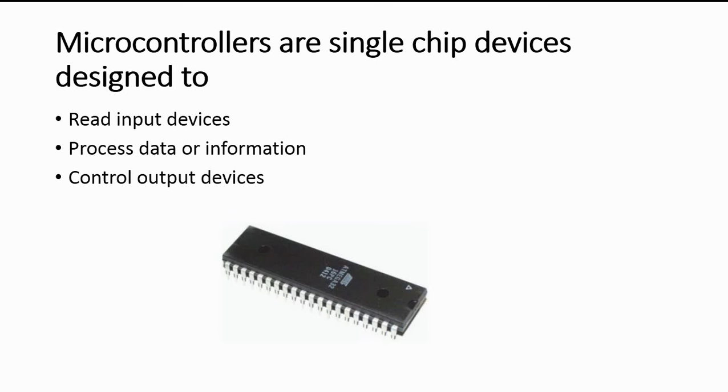some years ago they were not used for high voltage applications like home or industrial automation, where we have to control high voltages like 220 volt or above 220 volt. Because our generic relays or the electromechanical relays have a disadvantage of producing back EMF that can damage our microcontroller.